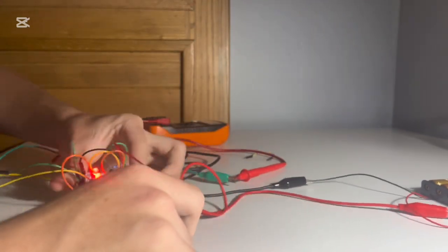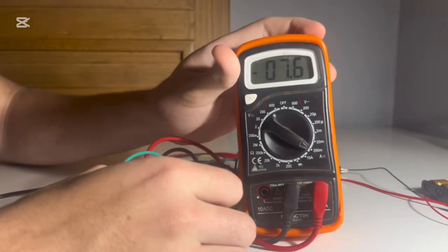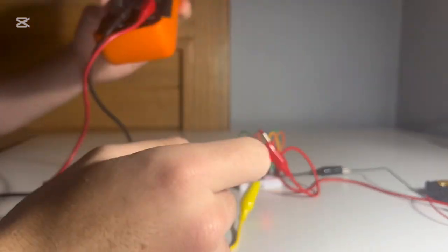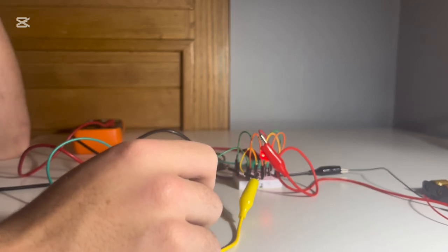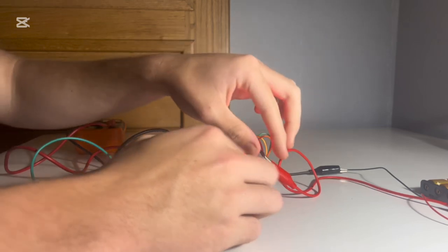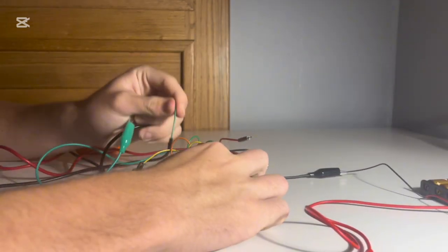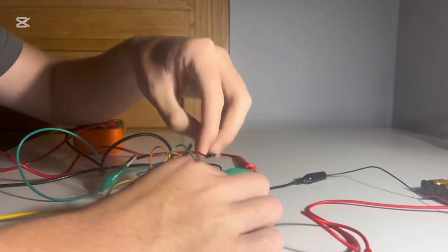We will now remove the ammeter and place it in series with the main circuit to test if it equals the sum of the two currents flowing into the branches just measured. We will thus reposition the ammeter next to the power supply and hope to get a reading in the region of 8.6 plus 7.6 equals 16.2 milliamps.